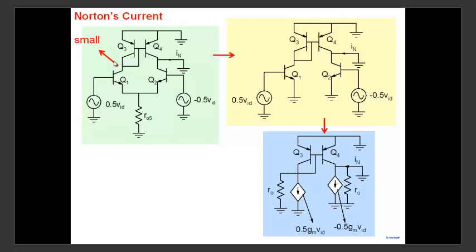So when you look below this particular part here, what you see is Q1, Q2, RD, and this voltage will try to make this node positive and this voltage will try to make it negative. Both are equally powerful and therefore this node will become small signal ground still. It's an approximation though, remember, it's not exact. So it's an approximation. I can still make this an approximate small signal ground.